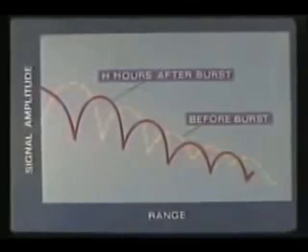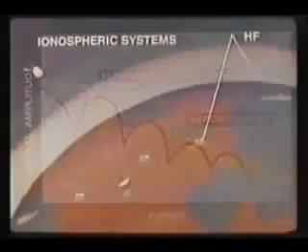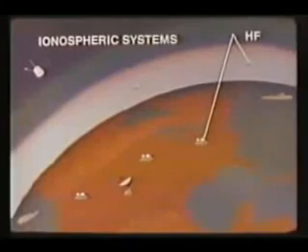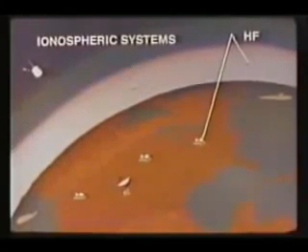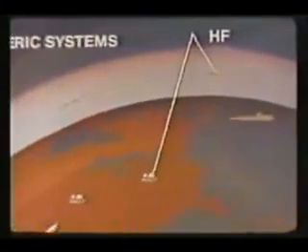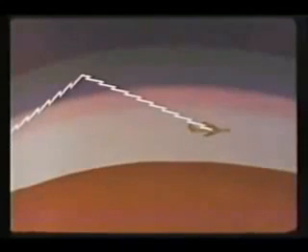Since the ionospheric D region is easily altered by delayed radiation from high-altitude debris, VLF circuits may be affected for many hours. In the high frequency, or HF band, reflections take place higher in the ionosphere, and the D region is strictly a region of signal attenuation. Thus, total system outage may occur for long periods of time if the D region is ionized by high-altitude nuclear bursts.